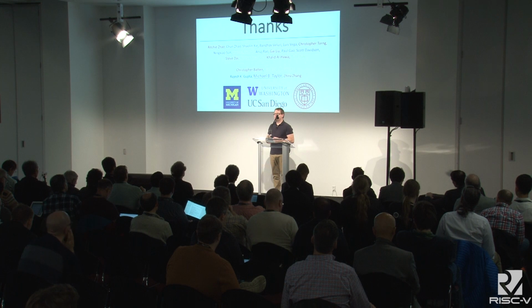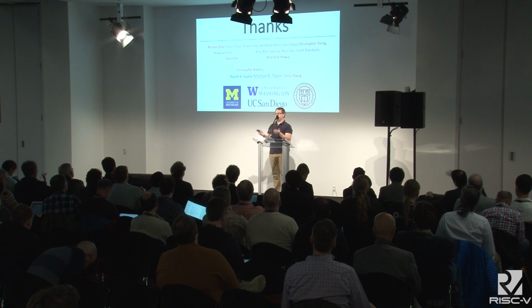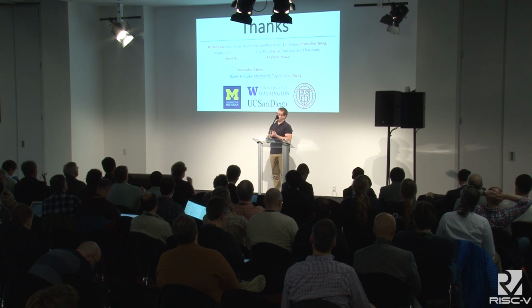So the question was, how much does it cost as an academic to do all the board designs? Well, do you want to design the boards or you just want to use our boards? Oh, the bill of materials for a board is like $350. If you want to assemble 20 boards, it'll cost you maybe $200 per board for the assembly costs. Obviously, the big ticket item would be the silicon, but you can do MPW runs to get the cost down there. Yeah, so we actually designed the boards to be very inexpensive. We don't use high-end Xilinx Virtex parts for our boards. We use Spartans to keep the cost down. Great, thanks a lot.